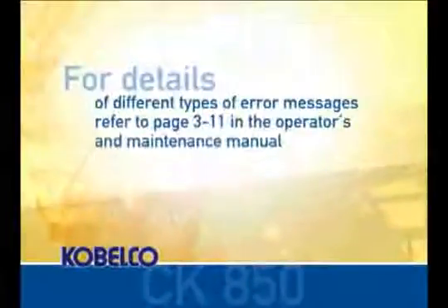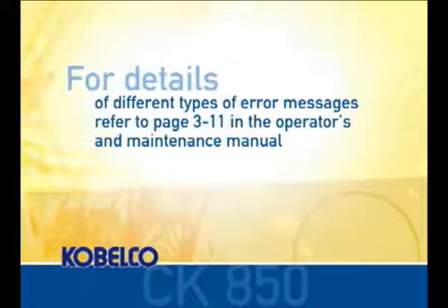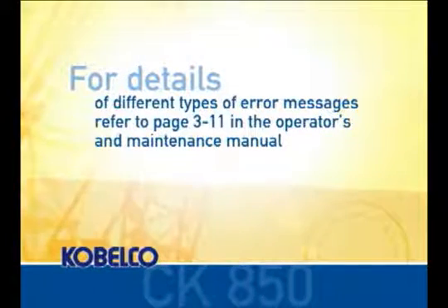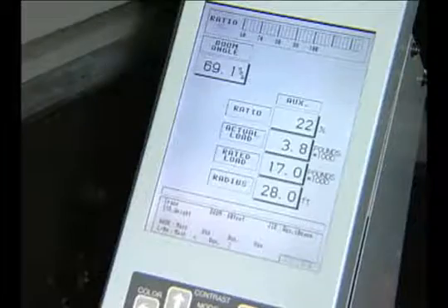This is the warning display bar. It will give the operator a visual message if one of the alarms is sounding, or will flash an error code if there is a problem with the LMI. For details of different types of error messages, refer to pages 3 through 11 in the Operator's and Maintenance Manual. At the lower part of the screen, the current crane posture is indicated. This allows the operator to confirm the current settings of the LMI at a glance.